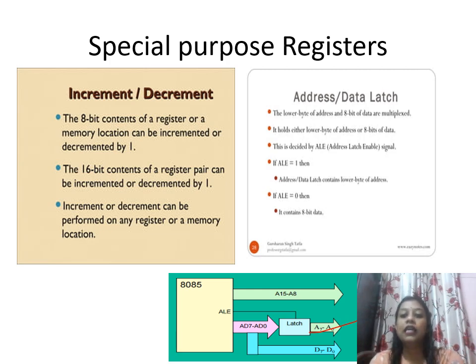This is used so that we don't need extra 8 pins for the data bus, and we multiplex the lower address byte. So this is a good feature, and this is done with the address latch enable.